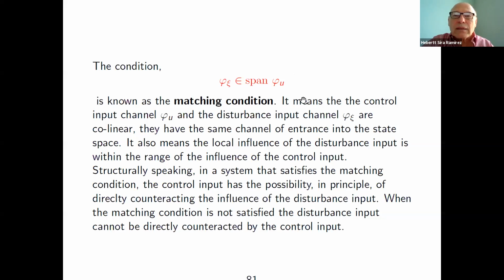This is one thing. The other area where this is valid is in nonlinear controller design. The zero dynamics, when you cannot push your disturbance to the zero dynamics and it's present in the same channel as the input, you better have these conditions satisfied in order to be able to guarantee that at least there is something you can do with that disturbance.